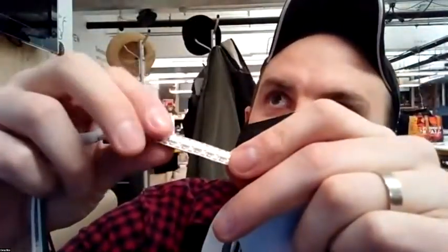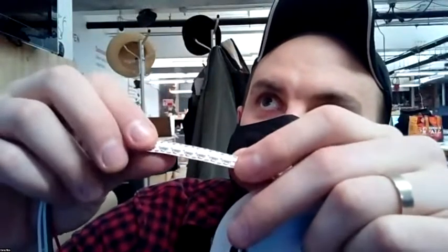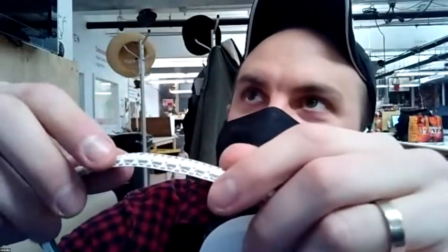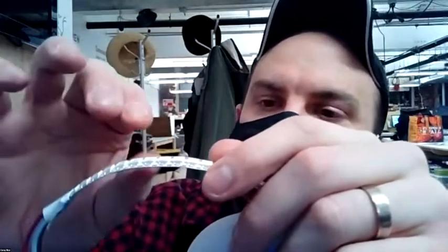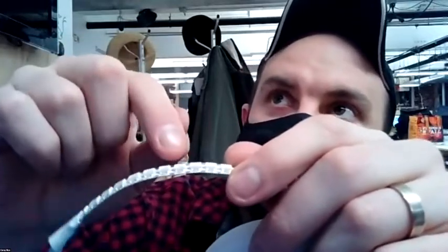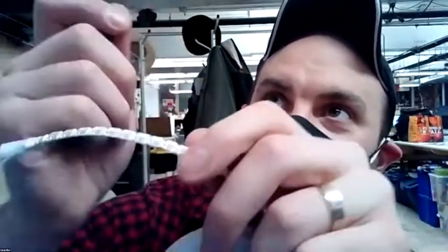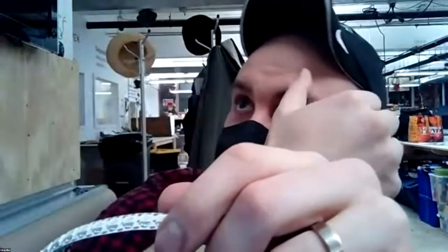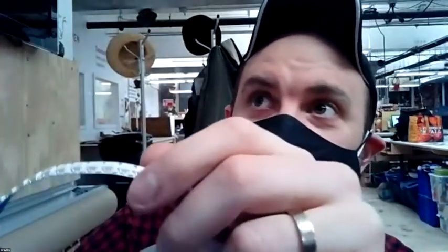Resoldering pieces and desoldering them from a strip like this is possible, even by hand. You just need to be very delicate with it, and it would need to be the solder joint that's failing, not the strip. If it was bent too aggressively and the strip is starting to fall apart, then you're going to have more trouble with it. Okay. It's possible, but repair is always tricky.